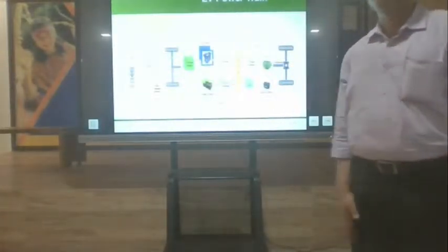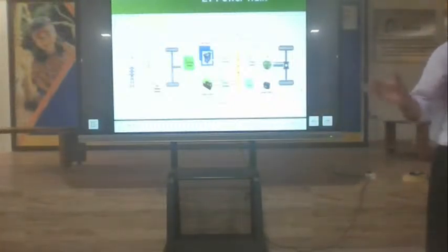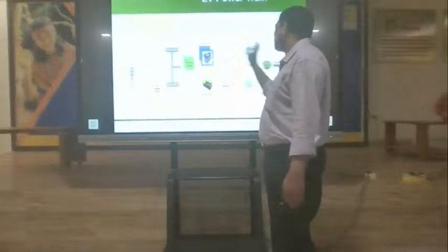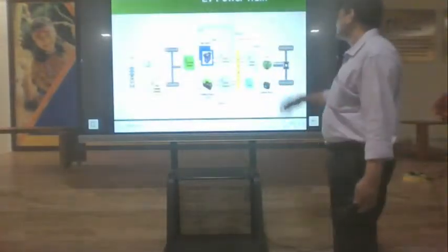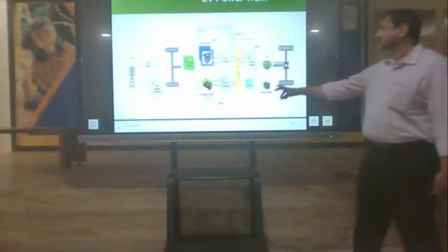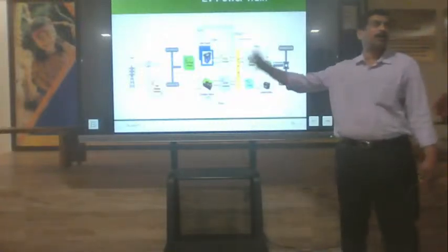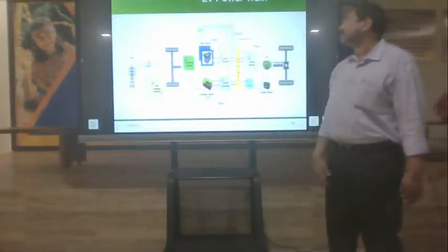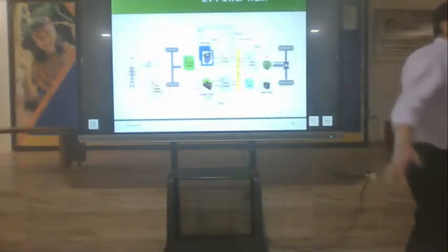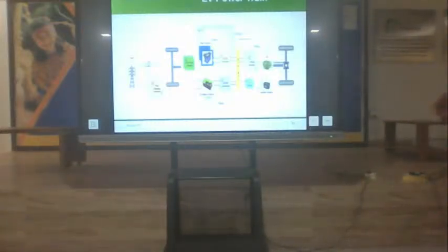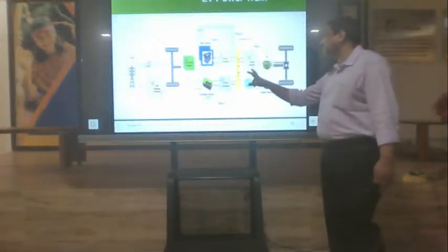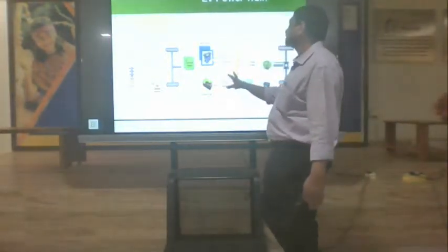Okay, in case of emergency, where the main battery goes down, you have all your control systems to work. There you have a low voltage battery, like your IC engines. In case of short duration, that voltage is boosted. That is your auxiliary battery. That is again boosted to the high voltage, and the high voltage runs the motor. This is the main power unit. They call it the power train. That is the main transmission unit of the electric vehicle. This particular motor, the three-phase inverter, and the high voltage DC bus is called the power train.